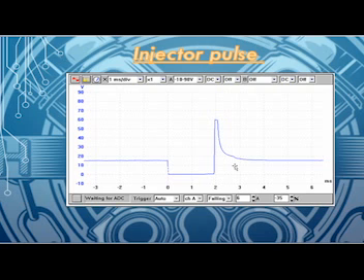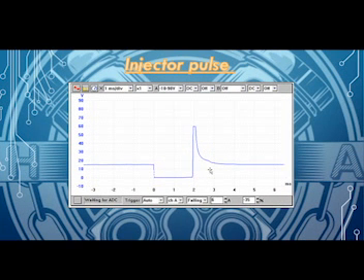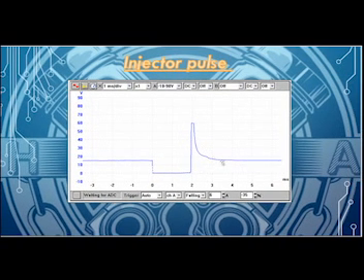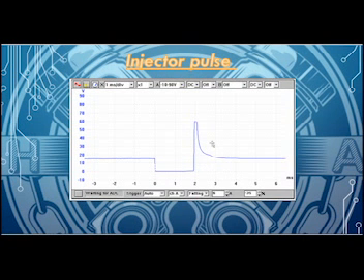If you are using any sort of diagnostic equipment to see if the injectors are faulty, a picoscope would be the best option, because you can visually see the operation of any component within a vehicle. If that little ripple wasn't there, it would indicate that the injector isn't working, so you would need to replace that injector with a new one.